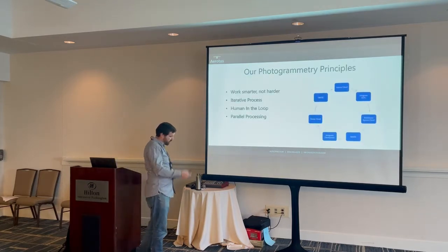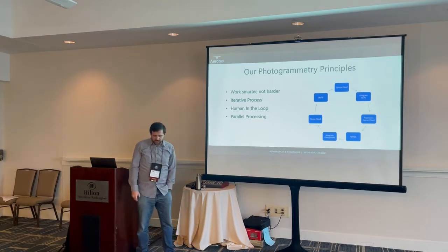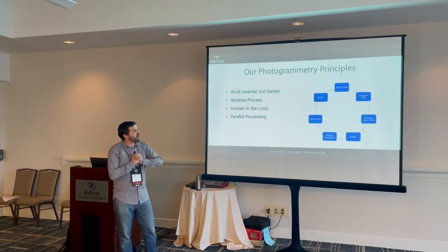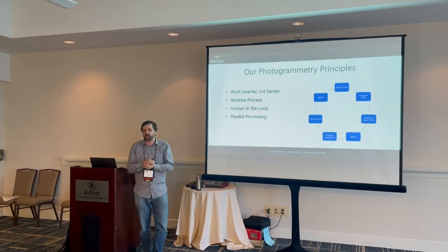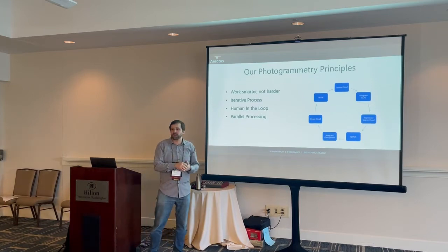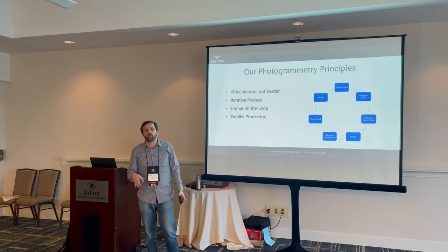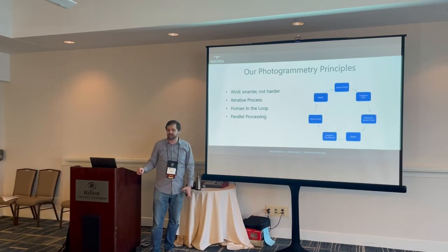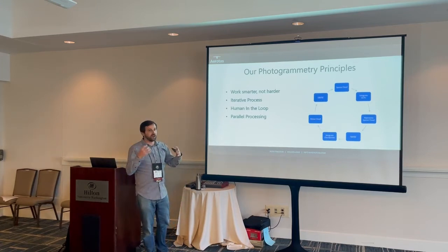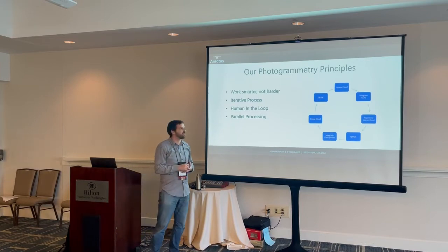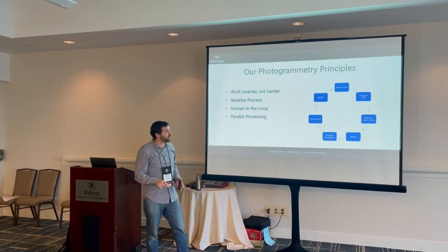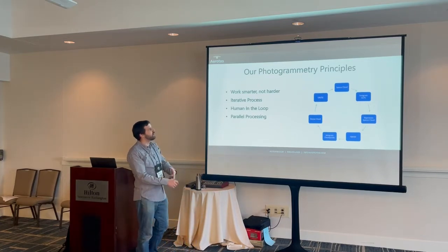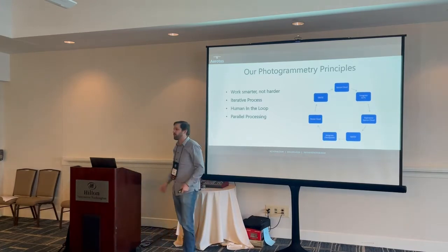Our principles for photogrammetry are a little bit different from LiDAR because it has that weird nature of being so computer time intensive. We have an iterative process for photogrammetry processing, where we process every project typically at least 4 or 5 times using slightly different settings as we recalibrate the camera to try and figure out the exact optimum camera calibration parameters and other settings to make sure that we get the highest accuracy possible. Processing that into sparse point clouds, integrating control points, reprocessing it, running QA/QC, running our check clouds, before creating dense point clouds and then running more and more QA/QC.